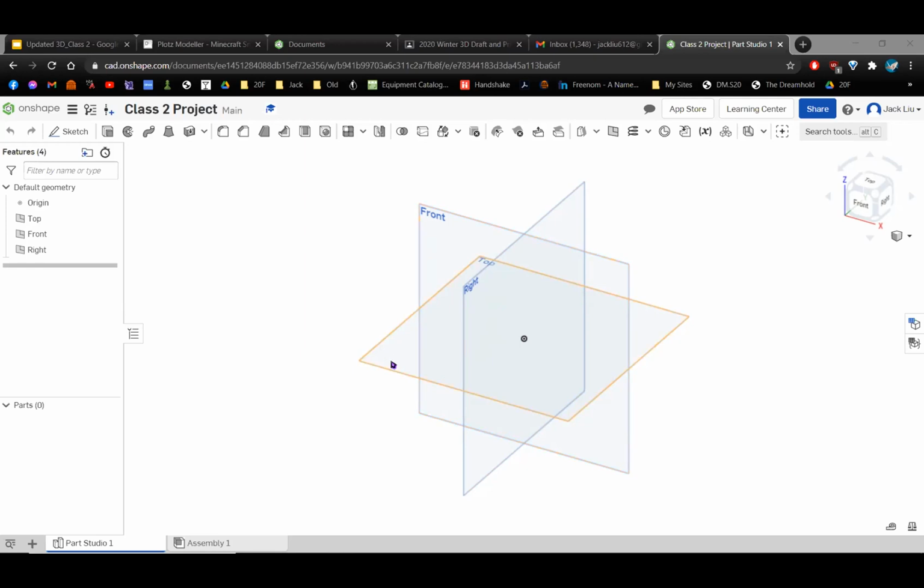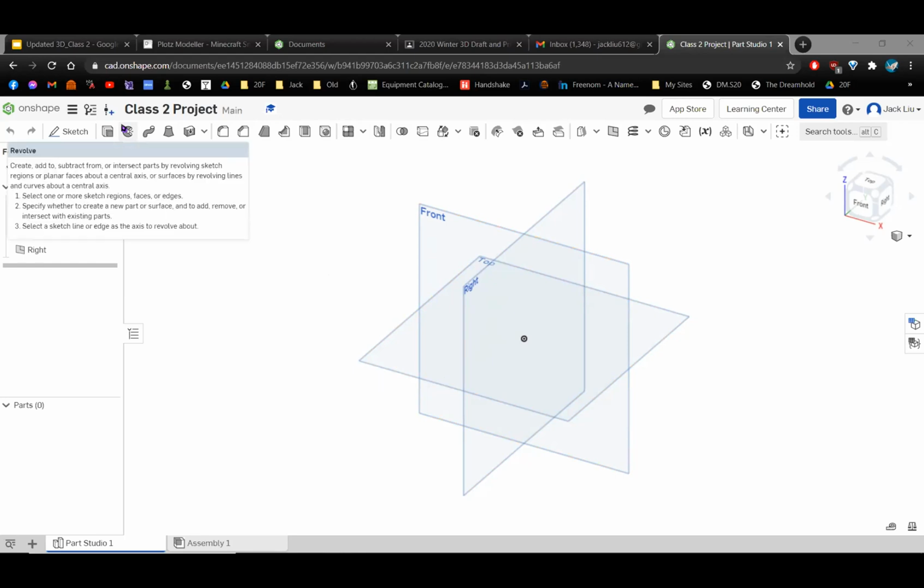So just as a review, starting off, we want to create a sketch, right? We want to create a 2D sketch. Right now we're in 3D view. If you look at the top toolbar, here are all of our 3D tools. We have extrude, revolve. These are some of the things we talked about before. But we want our 2D tools. We want to draw rectangles. We want to draw circles. And so how do we do that?